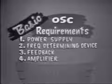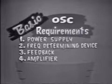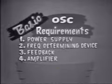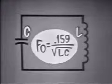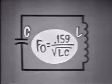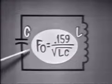First, of course, a DC power supply. It may be a simple battery or a very complex, carefully regulated circuit. Next, a frequency determining device. We have seen that an amplifier will oscillate without a frequency determining device. But the frequency is determined by distributed L and C, which makes frequency difficult to calculate and erratic. This kind of oscillation is usually undesirable. A frequency determining device, in this case the LC tank, provides a stable, easily calculated frequency.